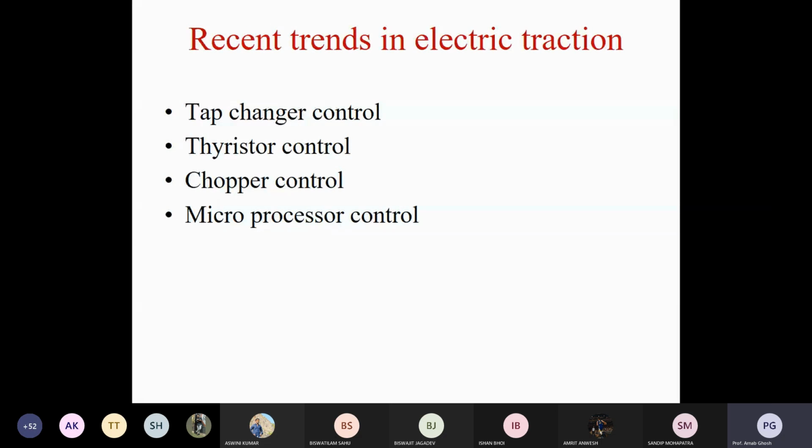All the time, if you try to change speed, you need to change the tap changer, so more flashing will be there. If you put it on the high voltage side, the flashing will be less, because the current is less and the voltage may be more. Changing the switch on the high tension side, the main problem is the additional stress in the insulation. But if you make the insulation good, there is no such flashing. Flashing may be mitigated or eliminated.